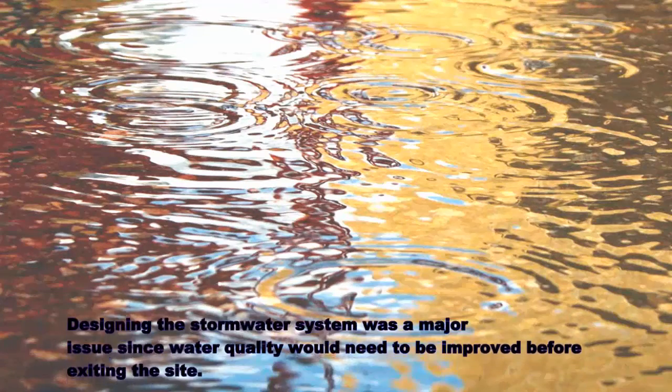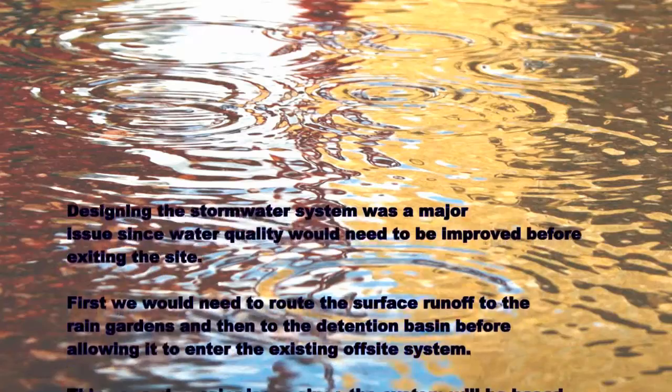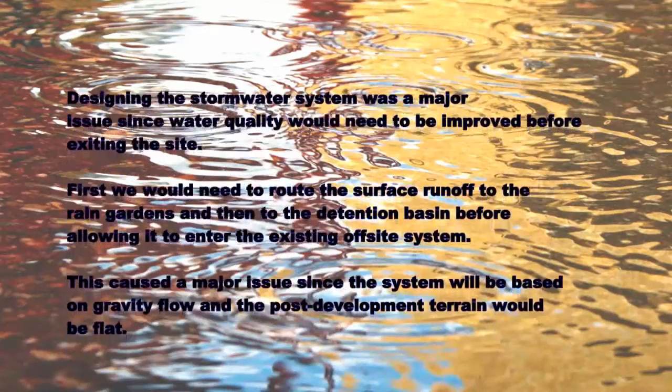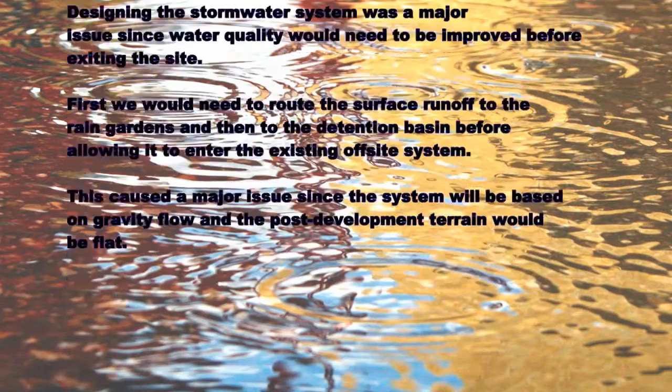Designing the stormwater system was a major issue since the water quality would need to be improved before exiting the site. First, we would need to route the surface runoff to the rain gardens and then to the detention basin before allowing it to enter the existing off-site system. This caused a major issue since the system will be based on gravity flow and the post-development terrain would be flat.